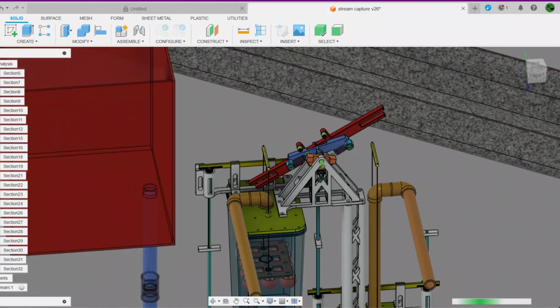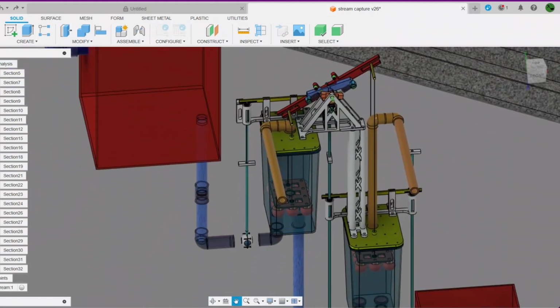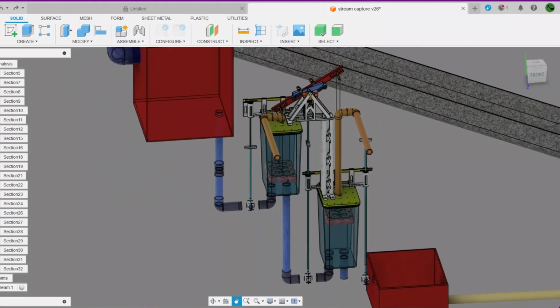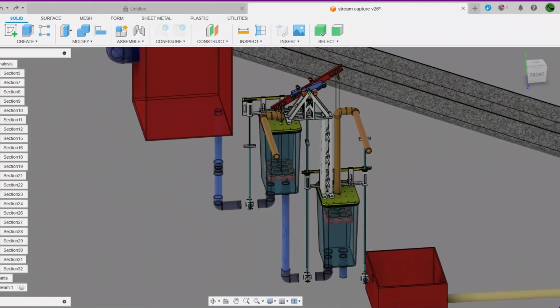Oh, and yeah, instead of doing this whole thing, you could just add limit switches, which would be way easier. You just have some sort of a buoyancy here, going through here, limit switch here, same here, limit switch here, then electronics, and then probably a solenoid valve, like a sprinkler valve. And then when this one fills with water all the way, the buoyancy hits a limit switch, which then tells the circuit to turn on valve 1, 3, 5, etc., and turn off 2, 4, 6, etc. And then when they drain to the next one, it hits that limit switch, and then it just switches.